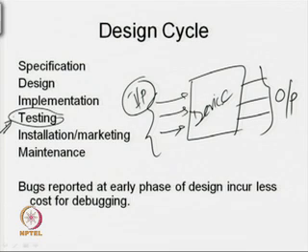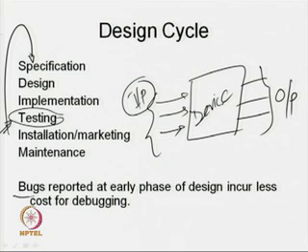So, in testing we are going to capture those particular issues also, and if the device is really faulty, then we have to discard it. But if it is having some functional error, then what will happen? We have to go back to our specification and revisit it, look for our design issues, and then redesign it. Once we fix the bug that has been reported, we again follow this particular path. We may have to do this several times.